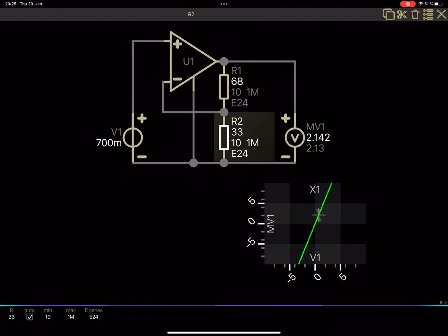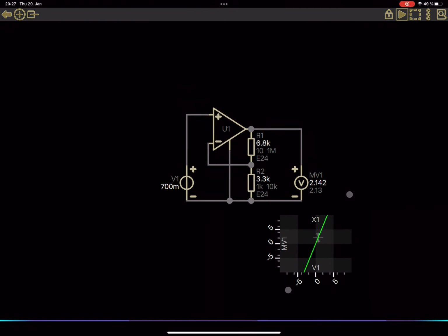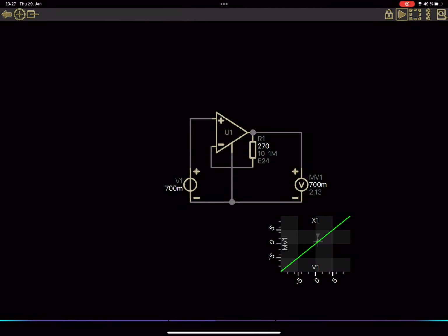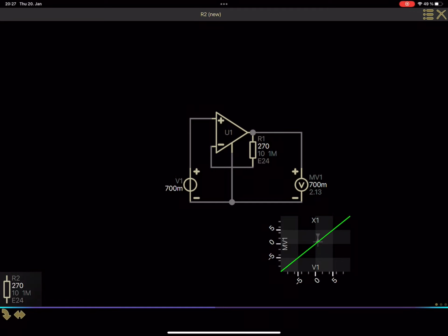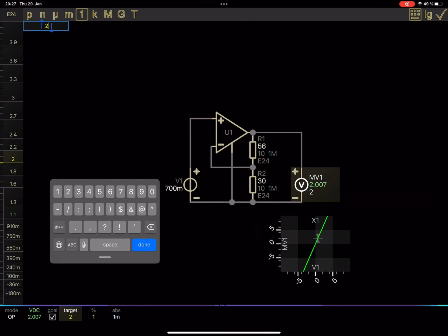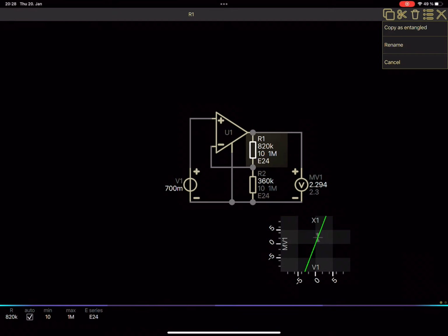A quick fix can be done by simply tightening the limits of an auto part. If you still want to define some sort of inner resistance as a design target, for example, if you want to ensure a precise operational amplifier bias current compensation, be aware that it cannot be done directly in the operational amplifier circuit. For such situations, CircuitShepherd provides the feature of entangled parts, or also called entangled copies.